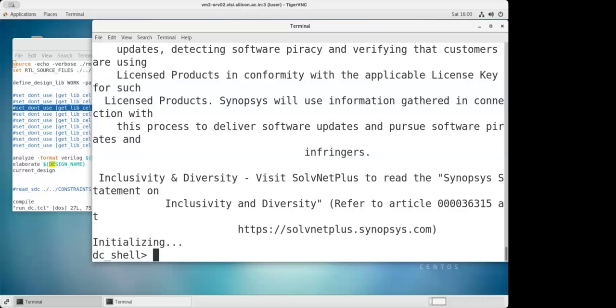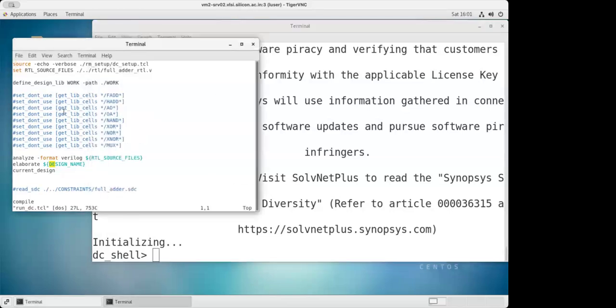So if you remove the DFF, then there is a problem, okay? Because in your design, in the RTL we are using positive edge. Yes, if positive edge is used, then a DFF will come. Sequential how? If you forbid the DFF, it might pick an SR and build a D flip flop from the SR. It will do something in that way. Yes, it will automatically do that part.